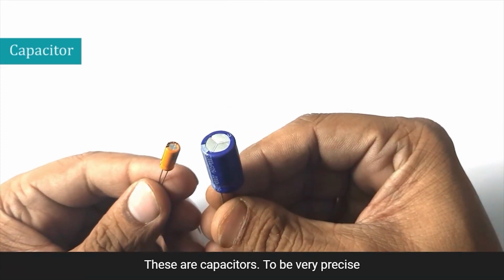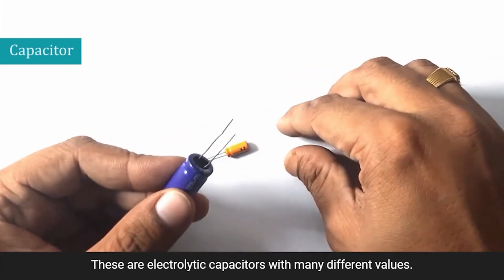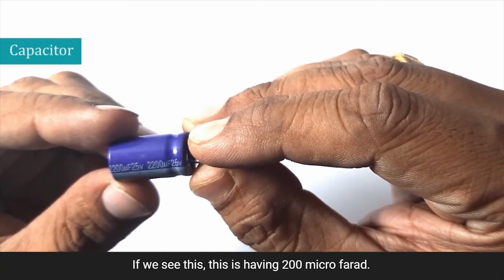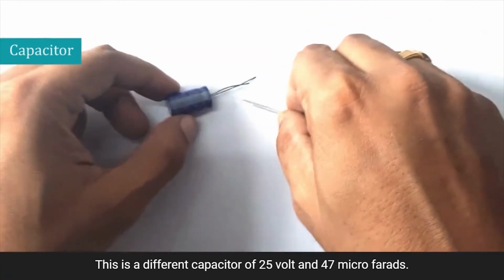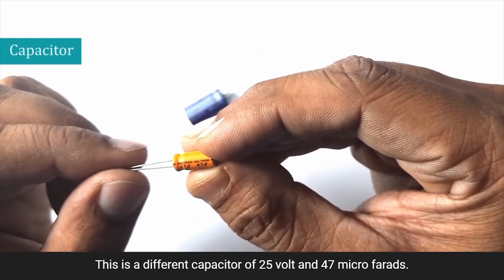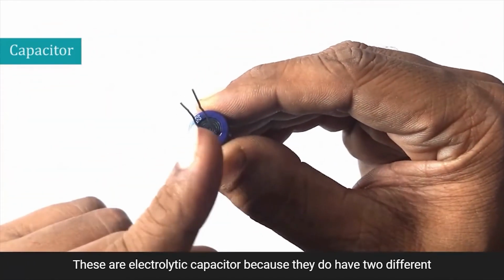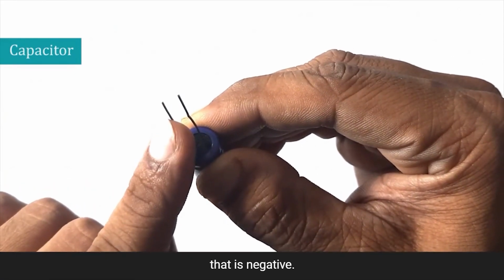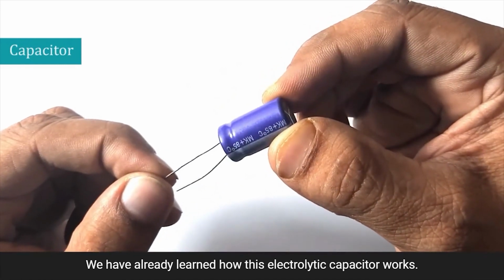These are capacitors. To be very precise, these are electrolytic capacitors with many different values. If we see, this is a 200 microfarad 25 volt capacitor. This is a different capacitor of 25 volt and 47 microfarad. These are electrolytic capacitors because they have two different terminals, the longer leg that is positive and the shorter leg that is negative. We have already learned how this electrolytic capacitor works.